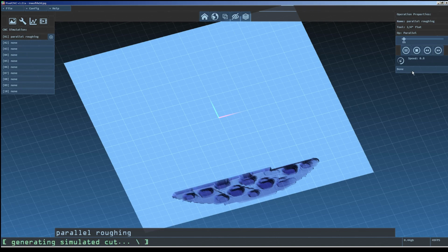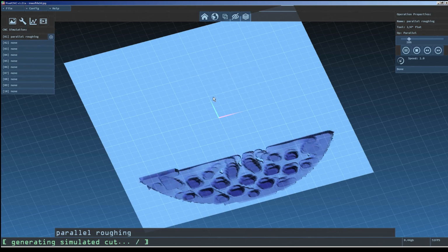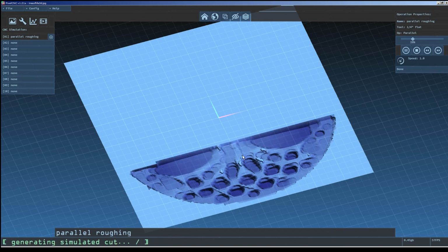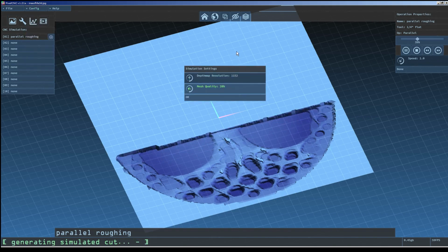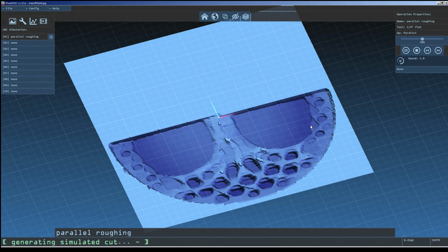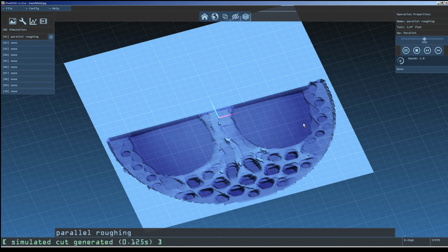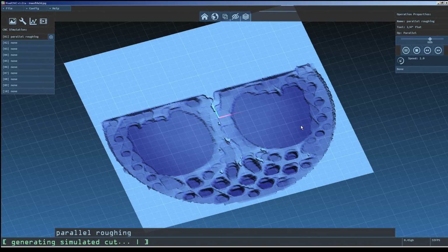The mesh quality setting affects the coarseness of the 3D mesh by controlling the threshold at which geometric subdivision occurs, which is the means by which the shape and form of the simulation depth map are conveyed geometrically. It is recommended users keep this as low as possible without sacrificing simulation fidelity too much to prevent excessive computations and memory consumption when running simulations. Certain situations may call for a simulation with more accurate geometry and benefit from increasing the mesh quality setting, such as a VCarving with fine details and features.